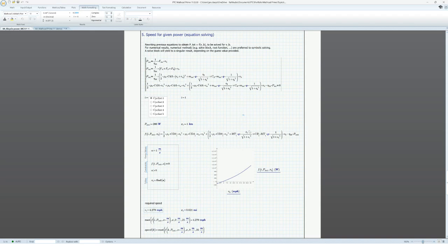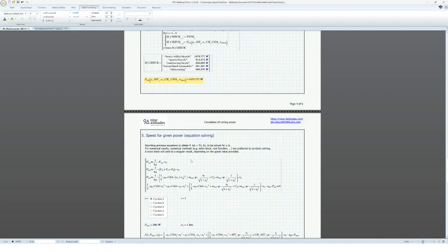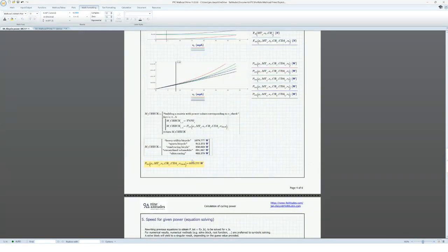For example, this result, we select it, and by right-clicking, we can ask to show the border. This will be visible when, for example, we print it to PDF, just to emphasize this result. This also works for entries in a solve block, for example, like this, right-clicking, voila, and we have the borders.